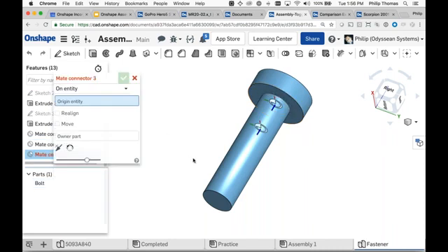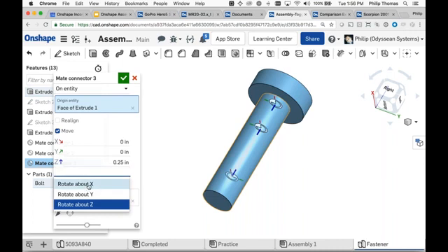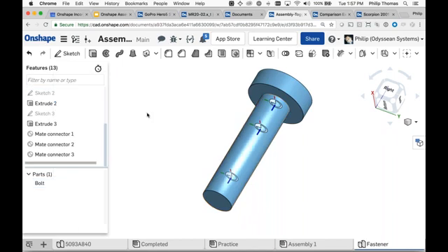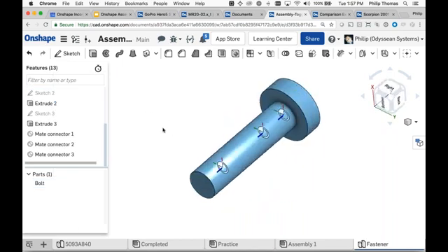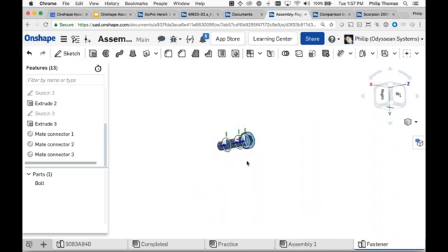Okay. And I'm going to hit Shift-Enter again. I want one offset from this endpoint by moving 1/4 inch. But I want the primary axis to be the other way. So I'm going to rotate the coordinate system about X by 180. And now my 3 coordinate systems are established.